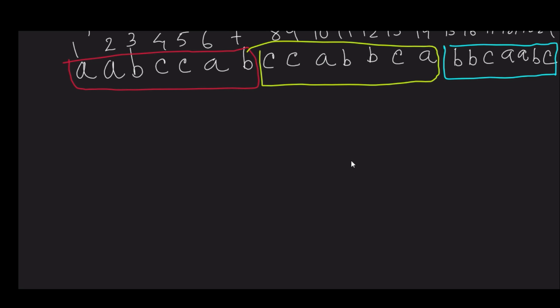Note that we can find out a definite pattern here. It is 2 1 2, like this is 2 conductors belonging to the same phase, then 1 coil that is different, then another 2 coil of the next phase, then again 1, 1. If you add these numbers, 2 plus 1 plus 2 plus 1 plus 1, definitely they will give you 7, and they should.